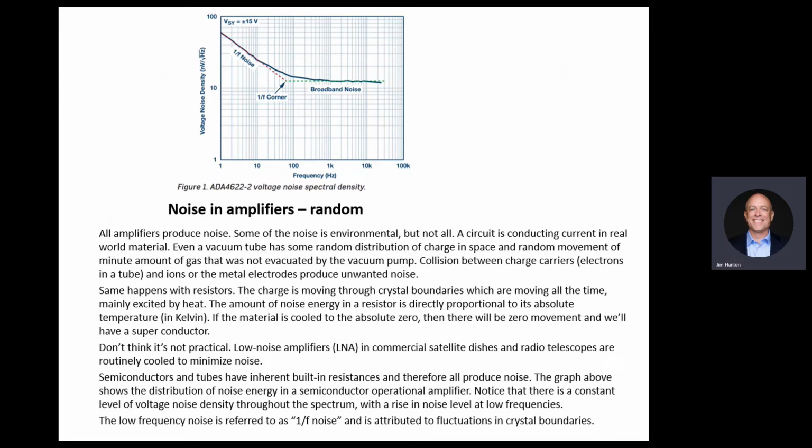Generally, we're talking about noise density, and again, it's technology, but noise density is really the power of noise across the frequency bandwidth. And the more bandwidth you use, the more noise you're going to get out of your amplifier. In phono stages, we are dealing with audio. The only thing that saves us a little bit is the RIAA curve, because it cuts down the noise.